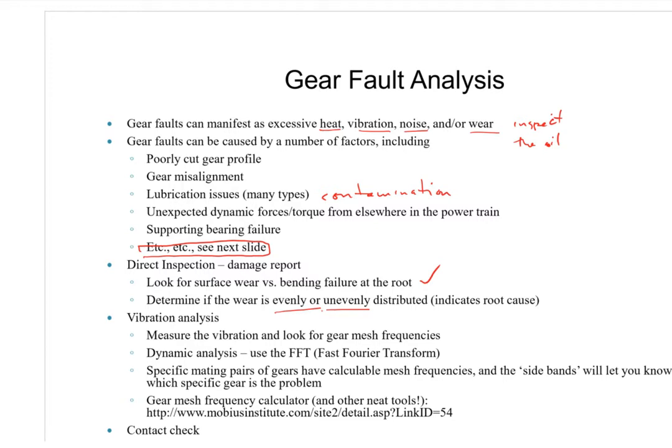You can also do a vibration analysis, measure the vibration and look for gear mesh frequencies.